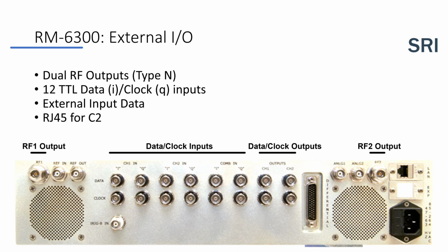Ethernet remote control, as I mentioned, we have a LAN remote control feature where you can basically connect to the unit with any web browser via TCP/IP, ensuring you're in the same network octet, and then ensuring optimal signal transfer.